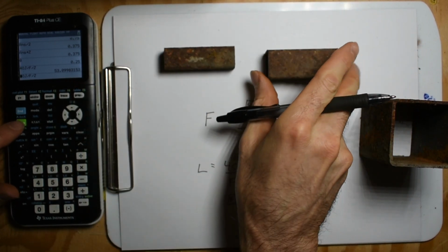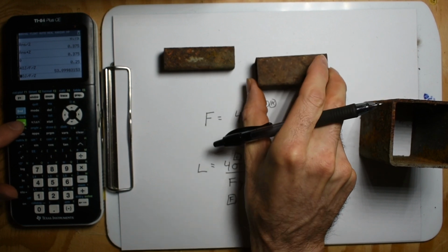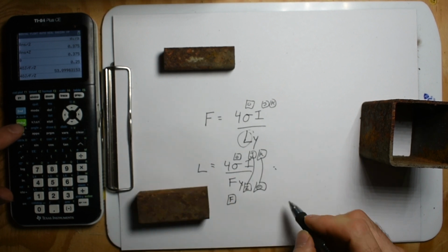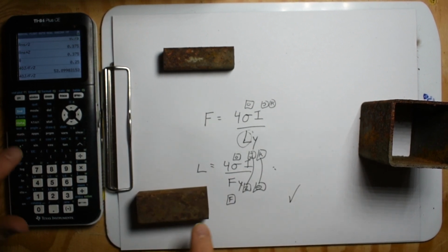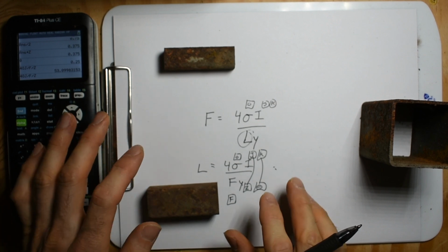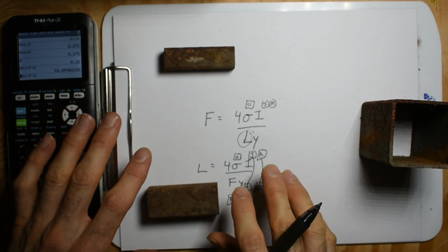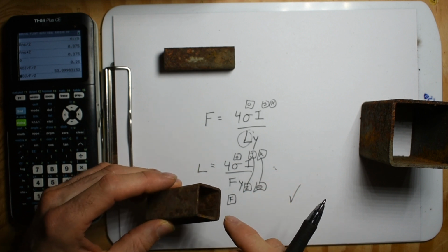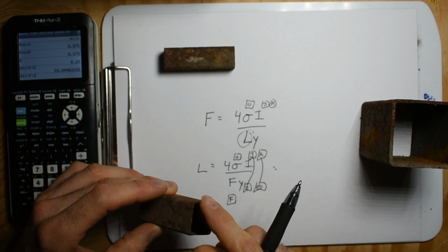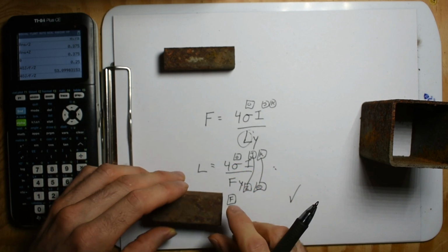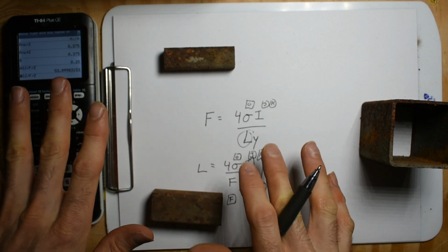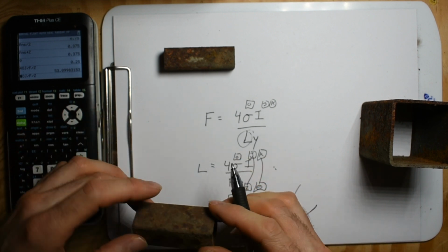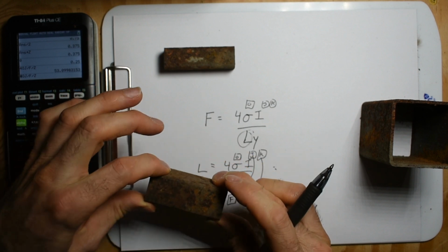So for this one, we can only have something that's a little more than 4 feet. And when I stand on it, we're going to be A-okay, but it's going to be right at that limit, right at that elastic limit. We're saying if we stand on it with 53 pounds in the middle, the moment is going to put max stress in this. It's going to put a 58,000 pound force on the top and bottom. The top in compression as it does a smiley face, and then the bottom is going to lengthen. And it's just fascinating, that's what's happening inside the steel.